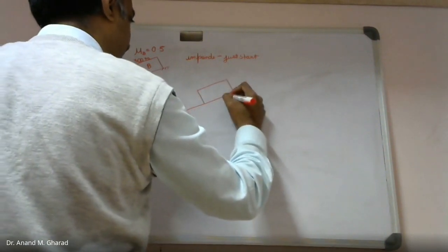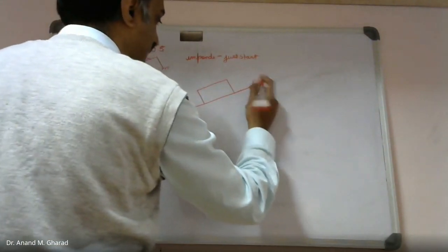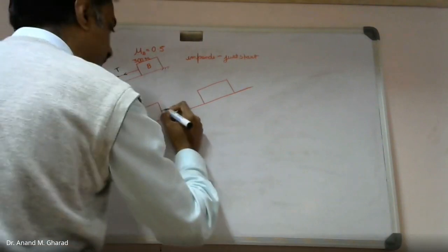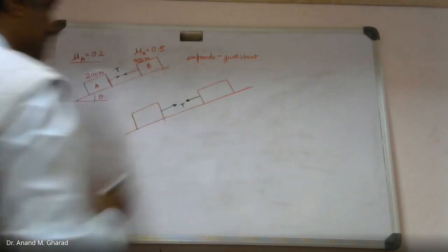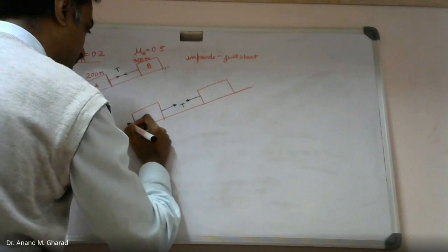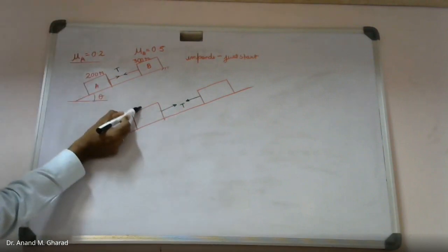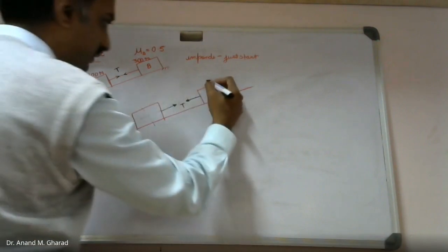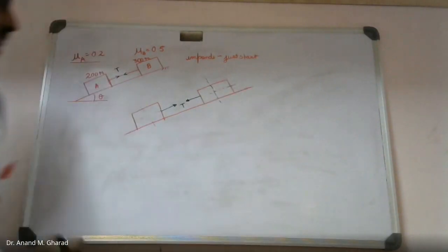So the free body diagram will consist of all the necessary information as far as external loads and forces are concerned; those will be represented. So this will be one of the external forces. Second, now let us freeze the axes. We will consider the horizontal to be x, and this to be the y axis.